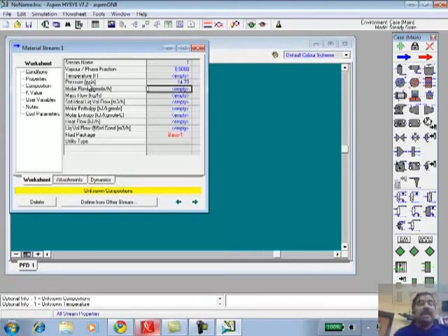Okay, and you will see in here, the yellow line here says unknown compositions. So this is where it is enforcing the degree of freedom that we have seen in analyzing the problem. Okay. Once the degree of freedom is completely specified, that is everything that it needs, if you have specified that, that will turn into green and it will automatically solve the problem under those conditions.